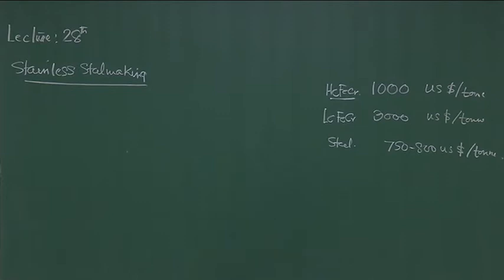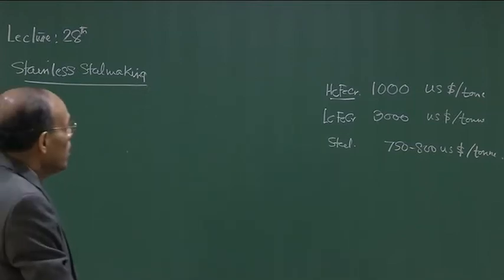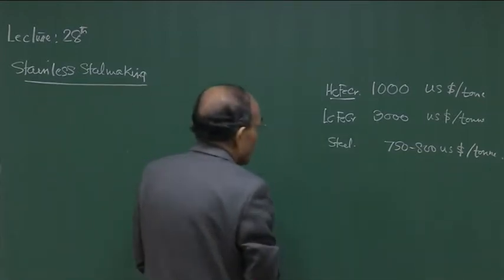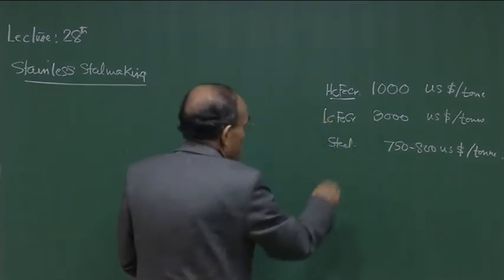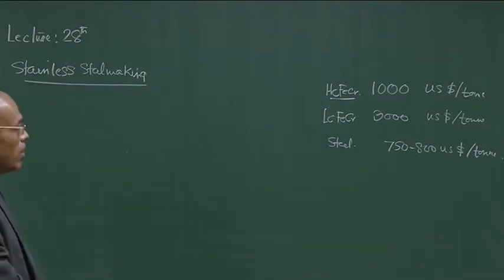You have chromium loss also. The slag will contain some amount of chromium, you will not be able to recover the entire amount of chromium because it tends to undergo oxidation. So, therefore, to circumvent such losses, efforts are made to use high carbon ferrochrome, and I think this price table clearly points out the decisive advantage that high carbon ferrochrome can offer in terms of better process economics.